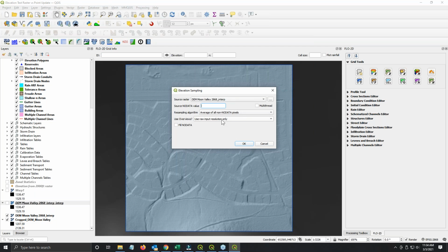the way that this works is it will use the raw input only. This is important because the default of a standard gdal warp is to apply the warp to the overview layer that is closest to the result layer. The overview layer of a raster is the indexed data that shows up as you zoom in and out on your map. So you have the raw data of your raster, and then you might have overview layers that show you a different picture at different zoom views.